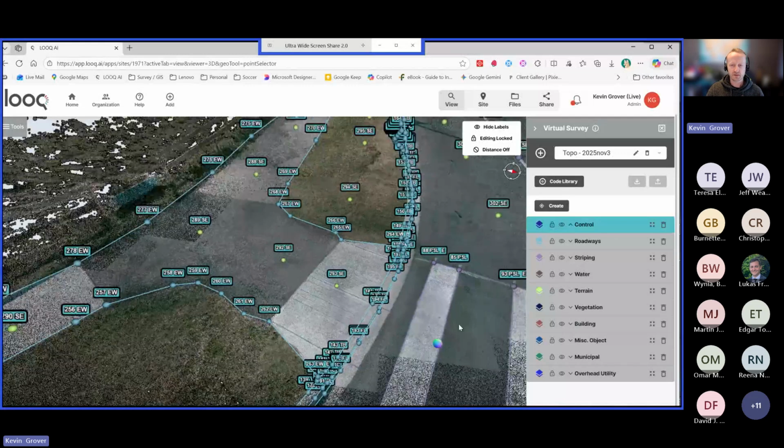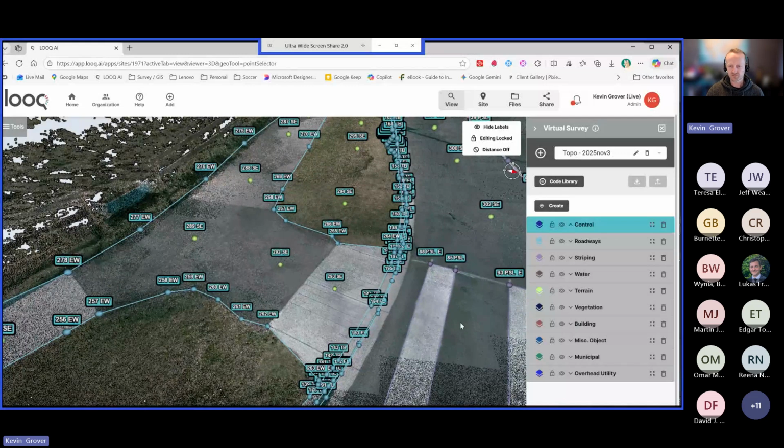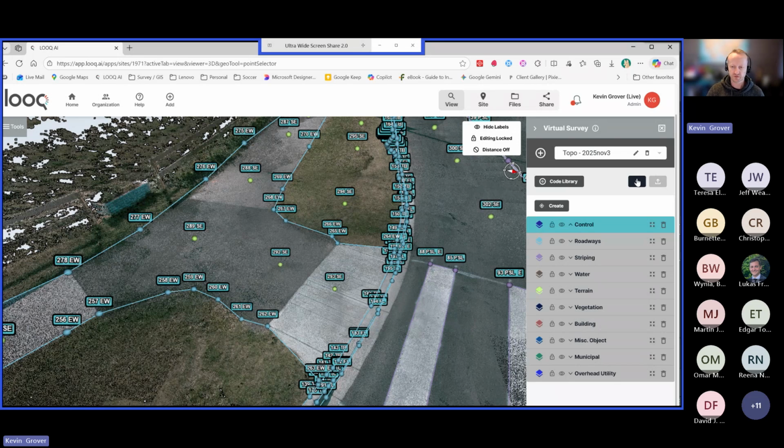So we've got a couple of ways to build a surface in Civil 3D. I just wanted to show you the tool out of this. It allows you to actually download this, which ends up creating just a CSV file of points. That's point, easting, northing, elevation, and then our descriptor codes. So we can also bring that into Civil 3D and actually create line work within the Civil 3D environment. So I just wanted to show you that as well, that we offer another tool set for doing some simple extraction.